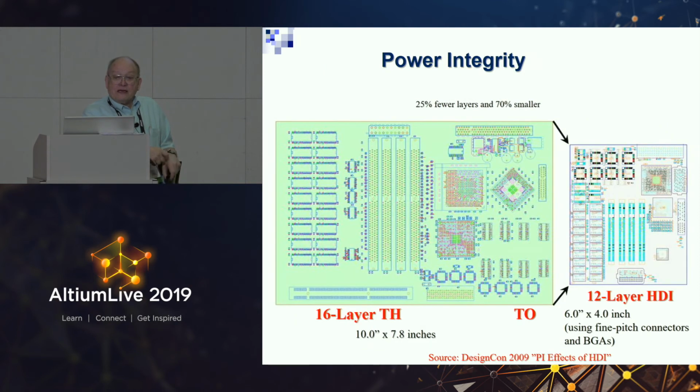With that, one of the things that I've done is I've taken this 16-layer through hole and made it into a 12-layer HDI board, but I've also built this in 4 different HDI technologies down to a 6-layer. So this afternoon we'll talk about 2nd and 3rd generation HDI.